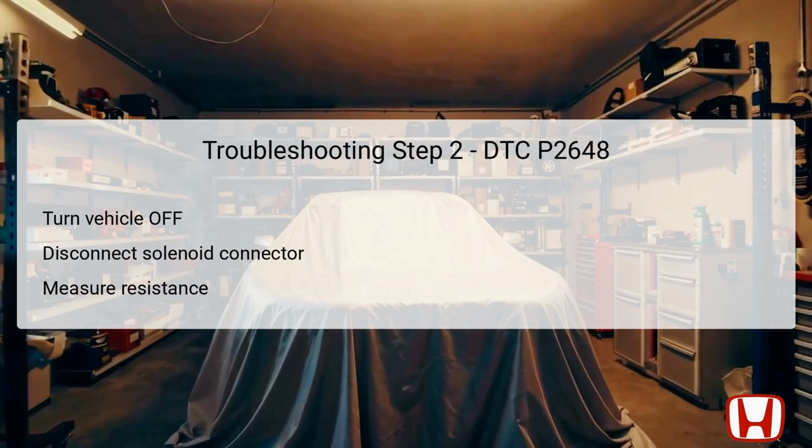Disconnect the 2P connector from the rocker arm oil control solenoid to perform relevant measurements without interference from the circuit. Using a multimeter, measure the resistance between specified test points on the solenoid's connector. Specifically, this involves checking between test point 1 and test point 2 at the connector side, which must be done while the vehicle is in the off mode.